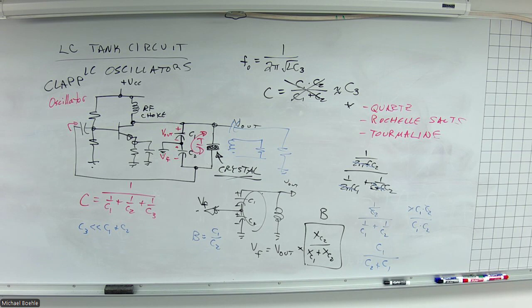So with a quartz, you get drift with temperature, age, all kinds of things. You'll get less with the crystal. Correct. And you have to find the crystal with the right frequency, or select the frequency you want and multiply it. You get a higher frequency out by using a Class C amplifier as a frequency multiplier. Start with a crystal frequency that's lower and create something higher.